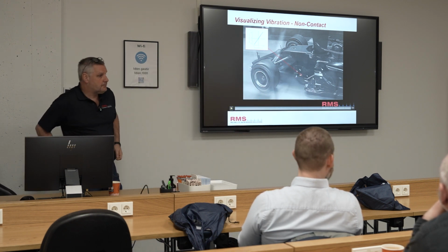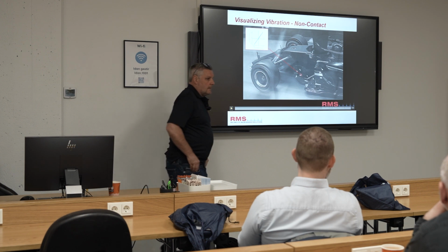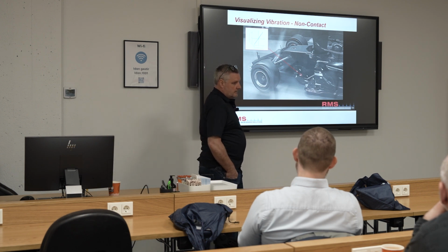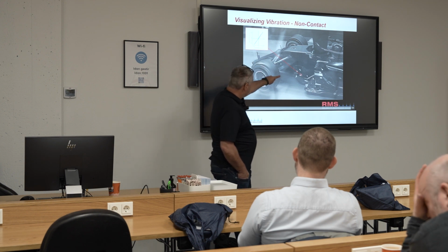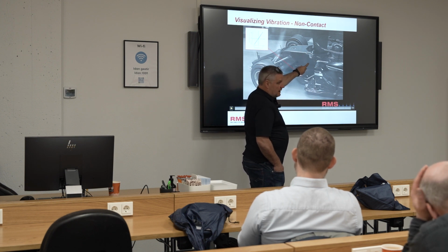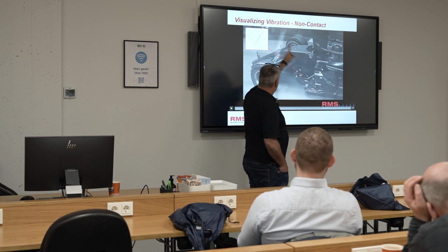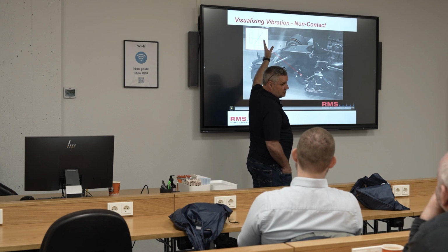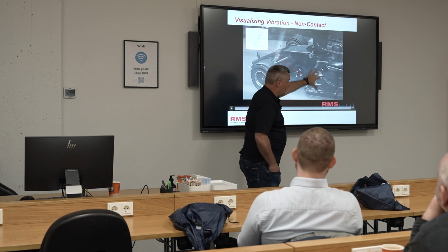So basically, with the camera you don't have to install any device, and you're not having to give it any clues on what's going on. It only watches the image. It's what's in the view. Now, I could put that measurement point anywhere in that image. So that's a dynamic measurement point? Yeah. So we can get that vibration signature, amplitude and frequency anywhere on that image.